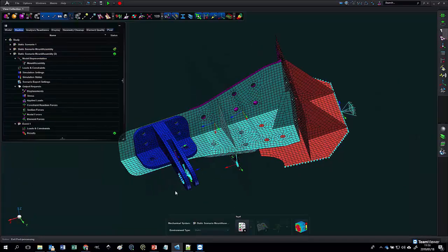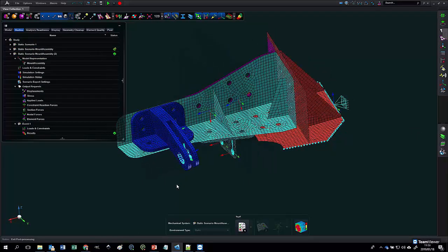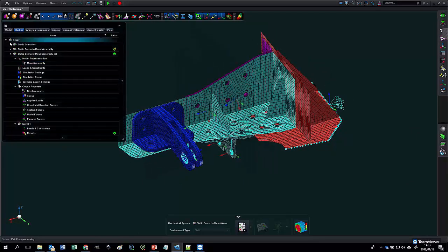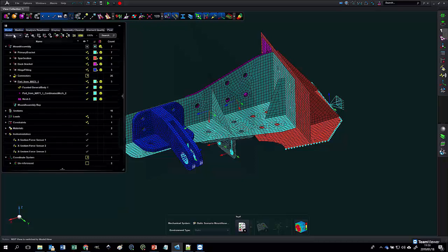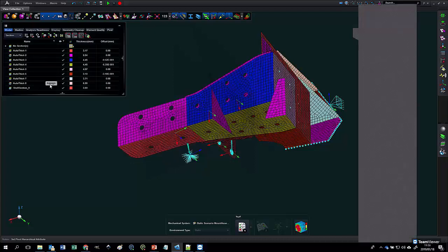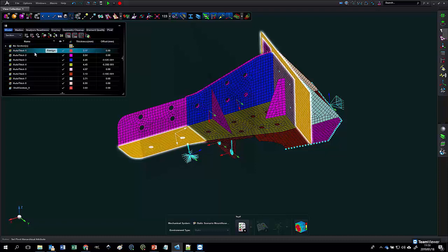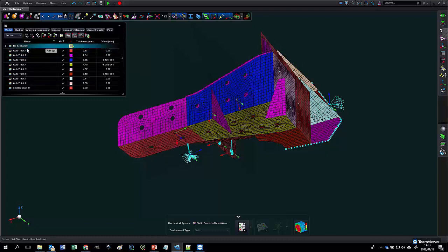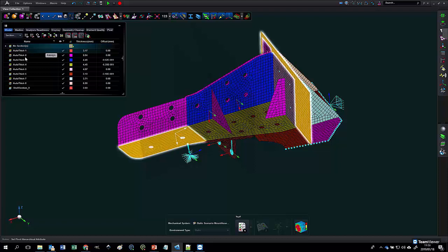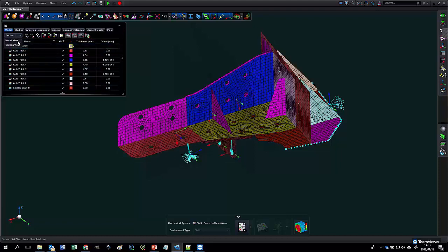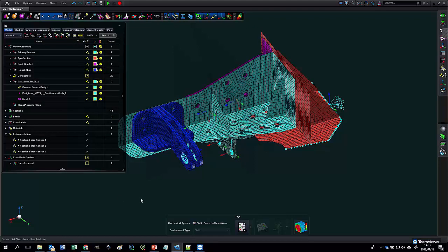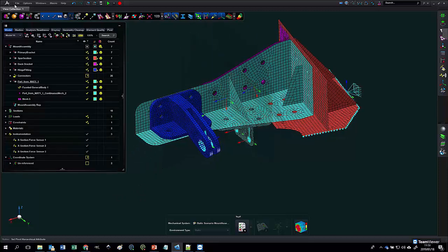Just a side note, for those of you who may not know, there's an ability a few releases back that in the modeler, there's a section view, which allows you to see all the section thicknesses and have them grouped. That is specifically useful if there's a section without a thickness and you can't find them. That could be quite difficult to find. Now you can easily identify them. So just be aware of this capability, because not many people are actually aware of that.